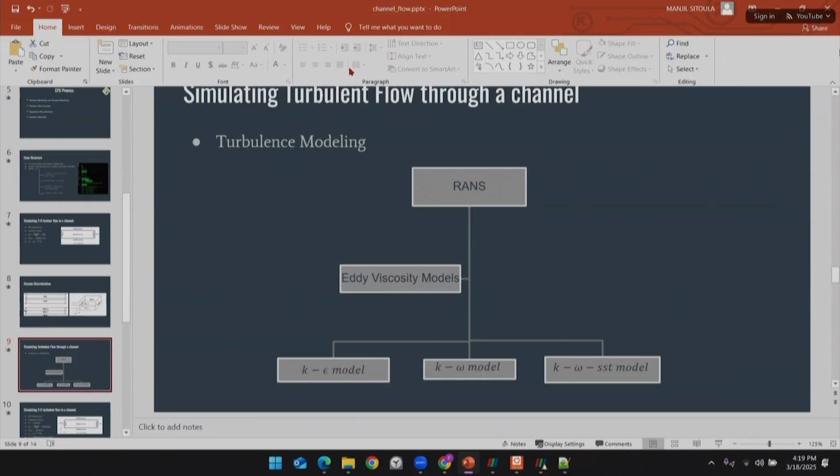I have one question. If there is multi-physics involved, like an ionic fluid that I have to solve for transport, I have to solve the Poisson equation for electrostatics. I'm talking from the perspective of microfluidics. There will be a creeping flow model, so I have to solve pressure, velocity, and electrostatics. The body force will need to be coupled from there. So this requires a different solver.